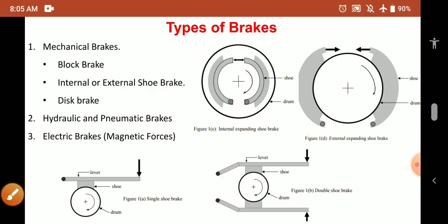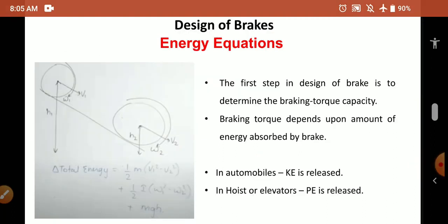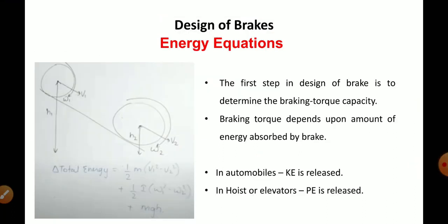Then hydraulic and pneumatic brakes. In hydraulic brakes oil, or in case of pneumatic brakes air is used to actuate these brakes, and in electric brakes the magnetic forces are used, eddy currents are used to operate this type of the brakes. The first step in the design of the brake is to determine the braking torque capacity. The braking torque capacity depends upon the amount of energy absorbed by the brake.